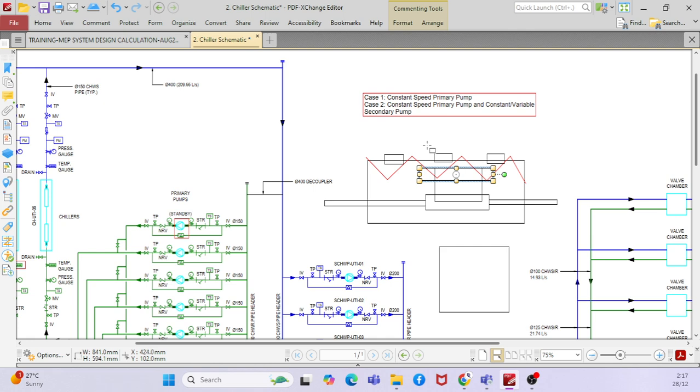If you go with a water cooled chiller, you can go to 3000 kilowatt, 4000 kilowatt or 6000 kilowatt. That means you can save the footprint. Say you have a very large building, a 10,000 or 15,000 kilowatt building. Instead of 10 air cooled chillers, you can go with one or two water cooled chillers to save space.